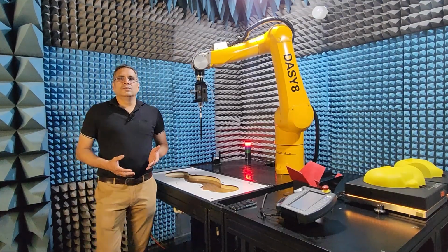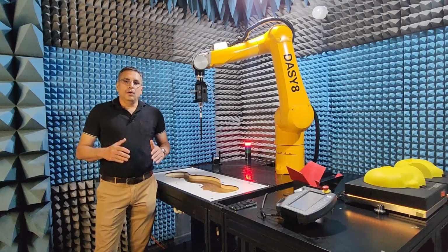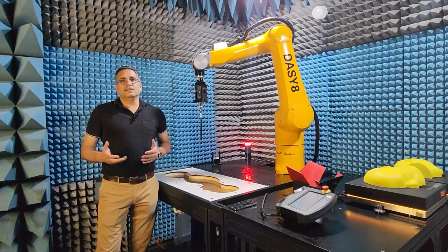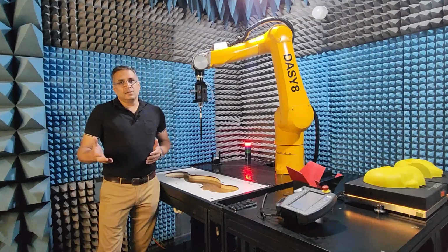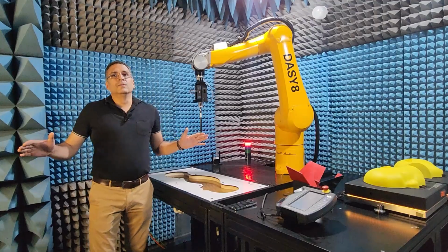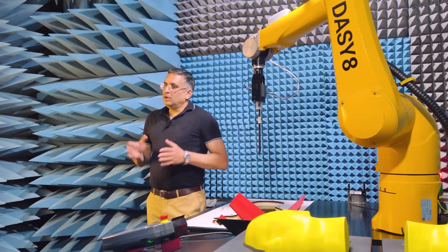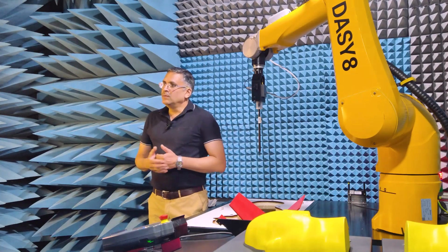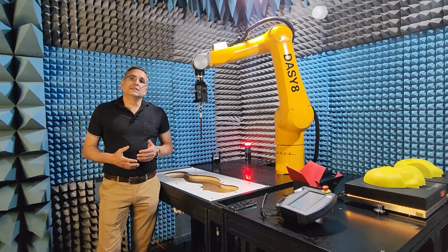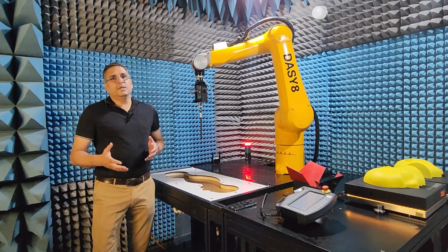This is a great feature for testing compliance of devices that can transmit simultaneously on multiple frequency bands. The current methods for testing such cases are typically either fast but overly conservative, or accurate but very time consuming. The fast approach is to sum the peak spatial SAR values for standalone configurations with the assumption that all antennae are co-located. This approach leads to a very strong overestimation and consequently to minimum transmit power.